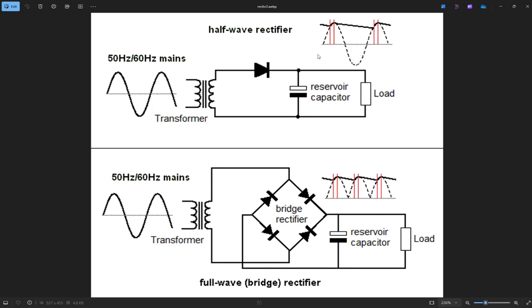Because you can see after the rectifier, the resulting DC has an amplitude very similar to the peak voltage of the AC. Okay, does that make sense? That's why we need a different type of transformer to convert that VM to a reasonable range, so we can rectify it, get a reasonable DC voltage for us.